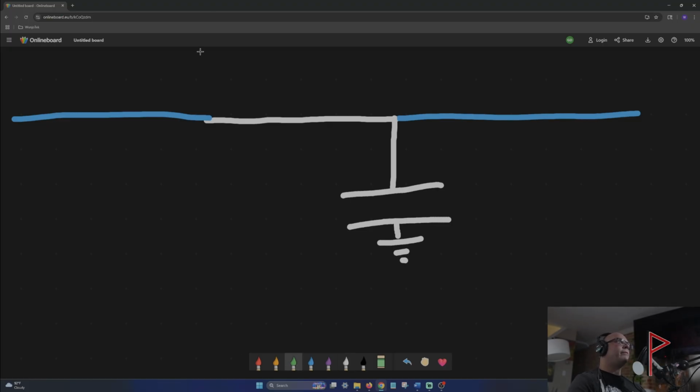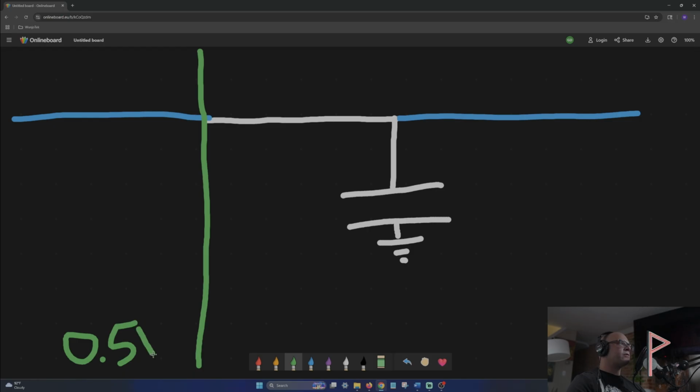Here's your bit line. And again, it's been pre-charged to 0.5 volts. So what happens here? Well, this is why we pre-charge, right? Because the bit line is pre-charged, the transistor is closed, and now what that means is part of that 0.5 volts is going to be flowing into this capacitor here. Okay, you see it filling up a little bit.